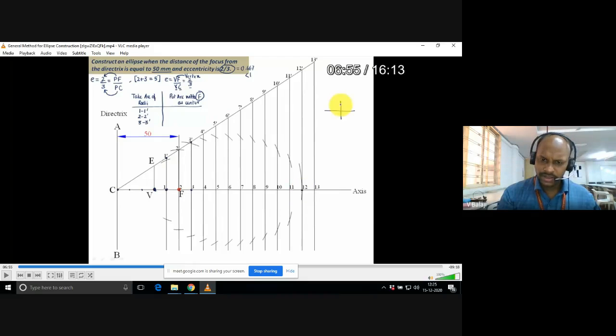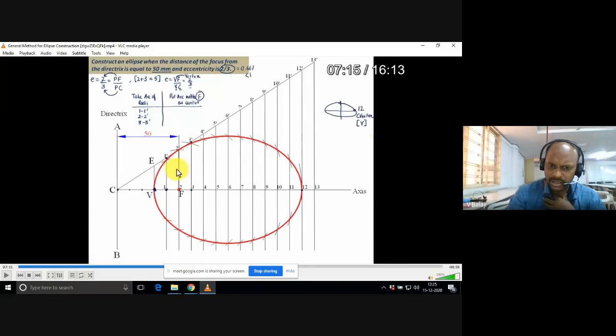Finally, you take an HB pencil. All these lines, whatever till now you have seen, are 2H pencil only, or H pencil. But at the end of the arcs, after getting so many intersection points, you have to join all those points with a smooth curve with your free hand. Okay, it's free hand only. No need to use French curves and all. Yes, sir. Free hand. Okay, you will find one point here, another point here, another point here, so many points.